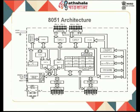So, this is the overall detailed architecture of the 8051 microcontroller. In all the controllers we will be looking at the ALU. This does the processing. Here also we have an ALU where the input is coming through the accumulator and another register. So, we have two temporary registers through which all the data that has to be processed will be sent, and one of the operands is always coming through the accumulator only.